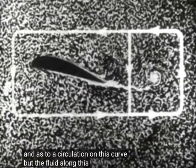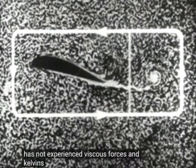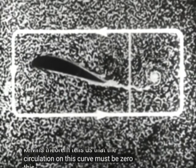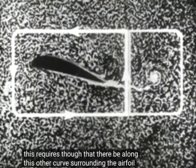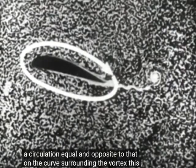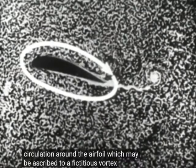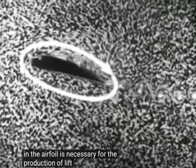But the fluid along this larger curve has not experienced viscous forces, and Kelvin's theorem tells us that the circulation on this curve must be zero. This requires, though, that there be along this other curve surrounding the airfoil a circulation equal and opposite to that on the curve surrounding the vortex. This circulation around the airfoil, which may be ascribed to a fictitious vortex bound in the airfoil, is necessary for the production of lift.